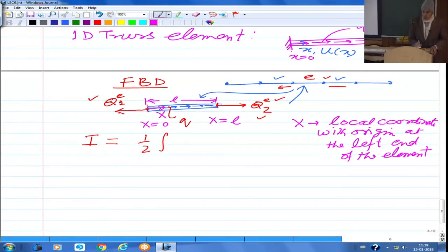So in a package, if you are using a particular element and you need to specify something with respect to the element coordinate system, or it takes some input with respect to the element coordinate system, then you have to understand how that package assigns element level coordinate axes. Either the first node is the origin, the direction from the first to the second node is the x-axis, then perpendicular to that in the same plane is the y-axis, and then perpendicular to the xy plane is the z-axis, and so on. Or the element coordinate system is parallel to the global coordinate system. So there are various options, but what we call this is the element level coordinate system. At this stage I just want to highlight that.